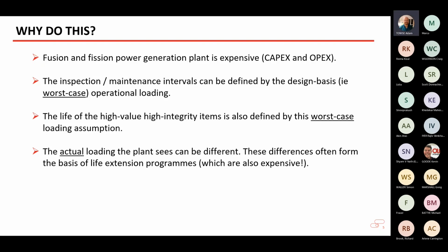And that generally defines the duration of your safety case, and there's periodic updates to that. But in reality, what the plant actually sees is potentially significantly less onerous than this worst case design basis that you've got. And the way it's done at the minute is this periodic update of the safety case often takes benefit from this difference between the worst case loading that you thought you were going to see and the less onerous case that you actually saw.